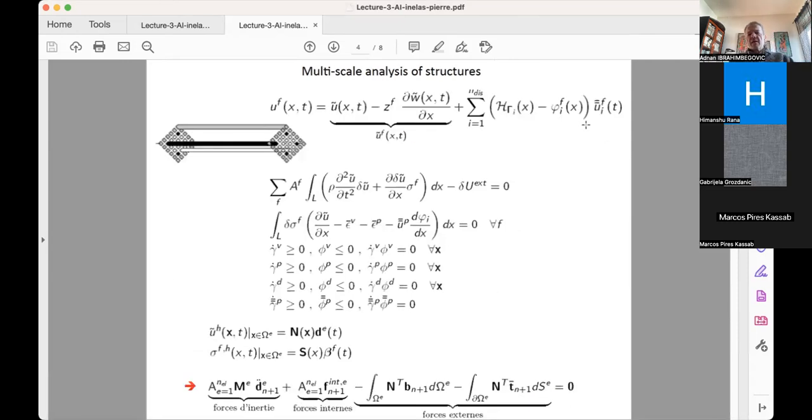So the way to keep the computation efficient was as such. We actually took a beam model and we built a multi-fiber beam model in 3D. A typical representation would be like a fiber reinforced composite. In the application we were looking at, there was reinforced concrete. So the black fibers are steel and the white fibers are concrete.